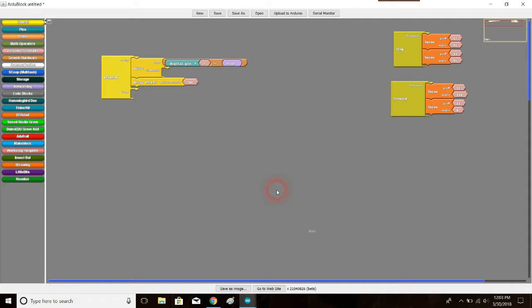The reason for that is, while I've taught my robot what these subroutines mean, I've taught it, well, when I say stop, you should do these two things. You should make sure this servo motor has angle 90 and this servo motor has angle 90. Hopefully, if your robot's calibrated correctly, that'll stop it.